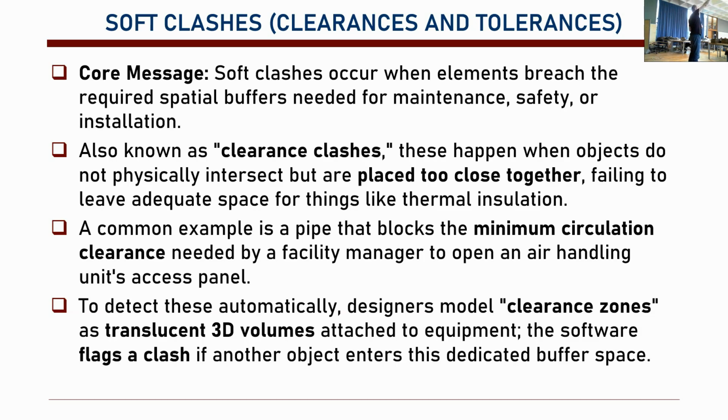You see that? The pipes above. These were added later, and they are awful, let me tell you. But they were added with space in between. You cannot basically design it so that the pipe is flush with the structural system. You need a space between. That is what we call a clearance.